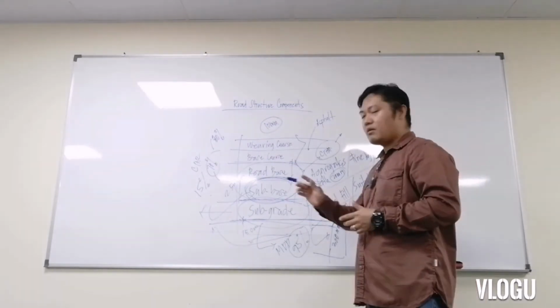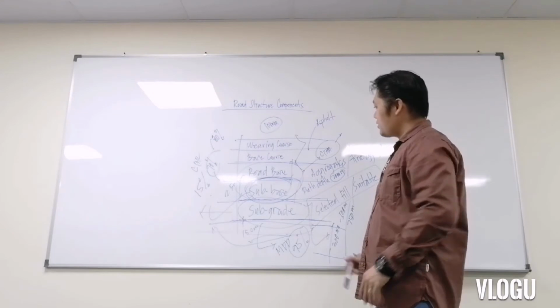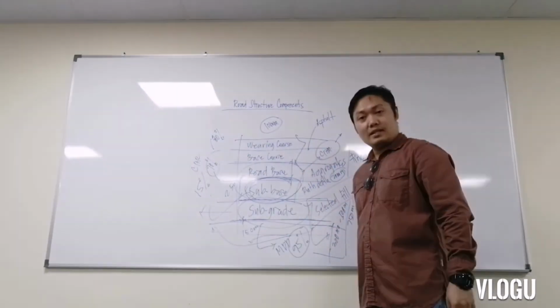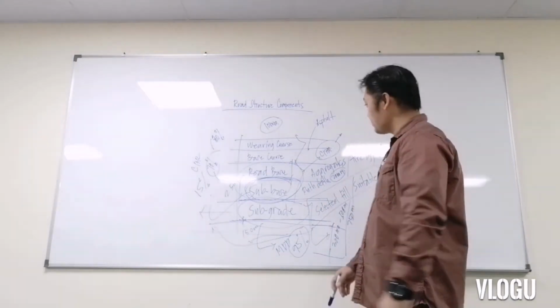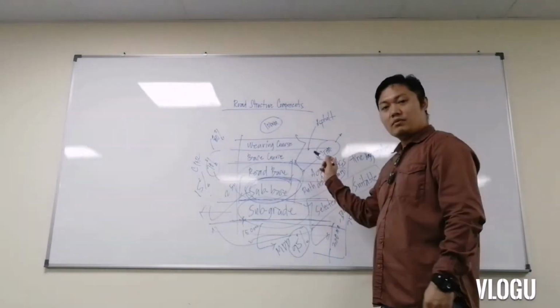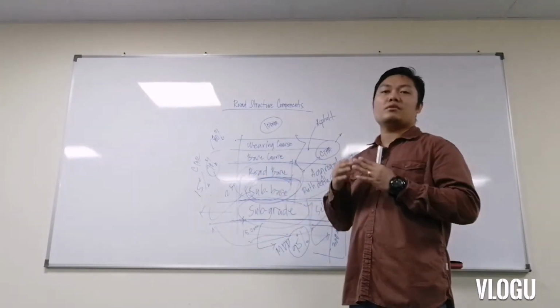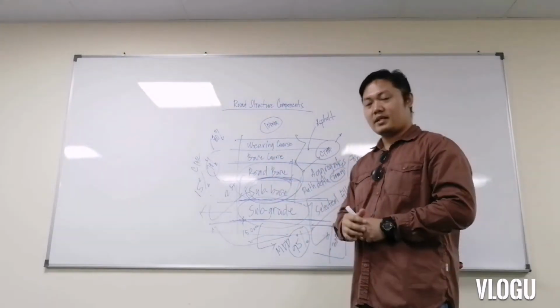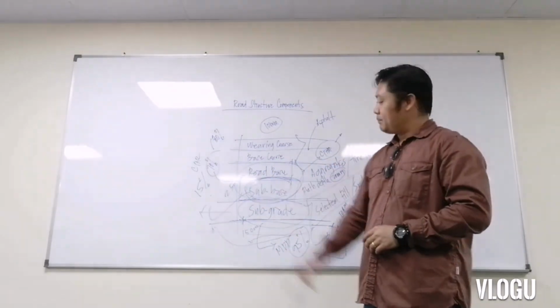So after we obtain all the process of testings and correlations, we have to start now the laying of the asphalt road base. Now, before we proceed with the laying of asphalt, we have to ensure that all of the surface preparation has been carried out before we spray the prime coat.